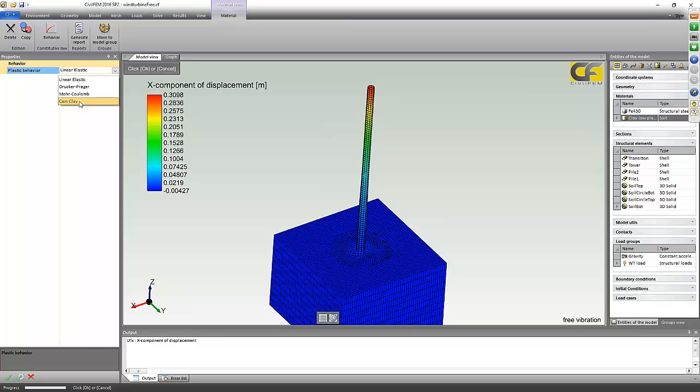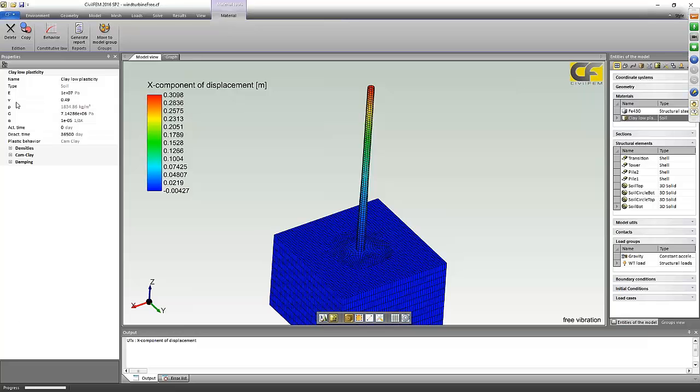For next versions, we will also have for Drucker-Prager and Mohr-Coulomb the cohesion and friction angle depend on plastic strain, and will have hardening or reduction of those properties. Well, clicking here we can play, set the properties and solve the model as we did.